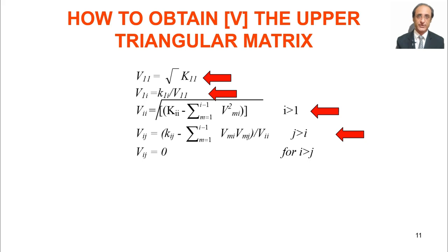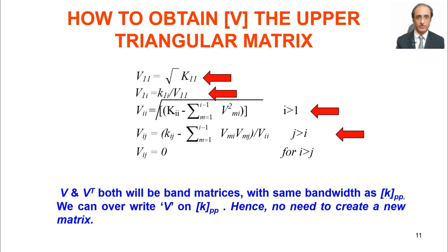So if we use this simple algorithm, then we can very easily get the displacements without actually finding the inverse. In fact, to get the inverse also we can use this algorithm. We can find the inverse also just by using this algorithm, you write the system of equations. See, a matrix multiplied by its inverse will give 1. So by that logic we can use this to find the inverse also. Okay, so this is the entire computational procedure.